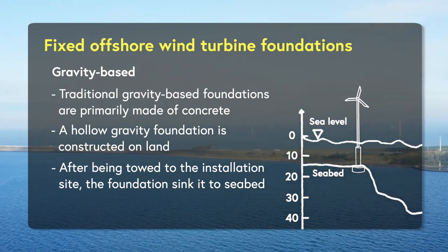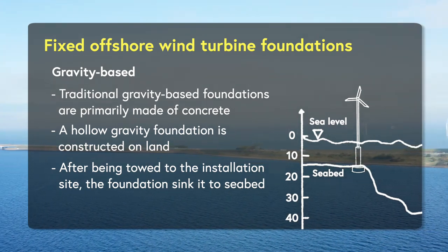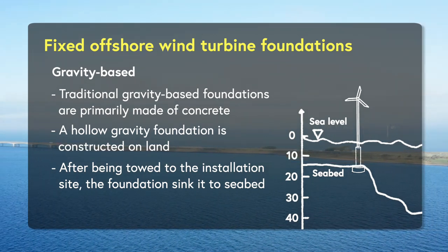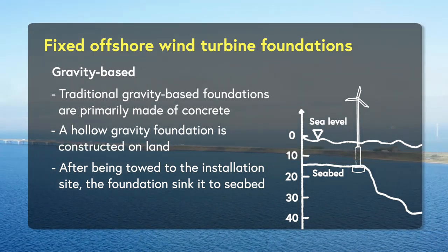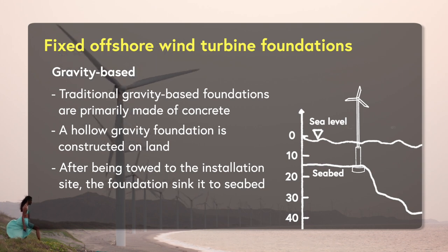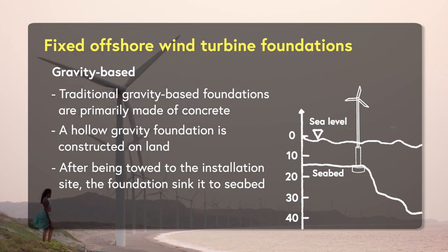As long as this foundation is heavy enough, is strong enough, then it can be a foundation for all kinds of structures. For example, when we build a bridge across a riverbed, sometimes we will use this type of gravity-based foundation. But you can see the disadvantage of this foundation is still obvious because it's not fixed on the ground, it's just a heavy weight.